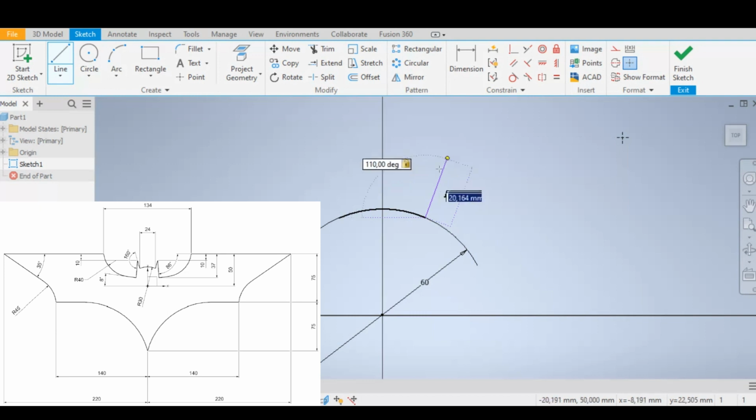So once you've done that, you can see our degrees are set, and now I'm just going to sketch wherever I want to on this, and you can see the length doesn't really matter, and I'll show you exactly why that won't matter to us. So from this you can see our line continues, and if I head down to a 90 degree angle, we have a 20 degree offset.